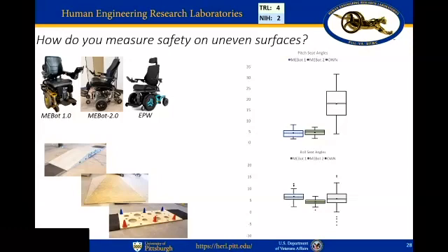But what was interesting to see is that when driving over around a 10-degree slope, you can actually see an even higher angle of almost up to 30 degrees. And why is that? It's because sometimes wheelchair users actually have their seat tilted already when driving over these environments. What I wanted to point out here is that MeBot still shows some seat changes, but it wasn't as much as compared to their own device.